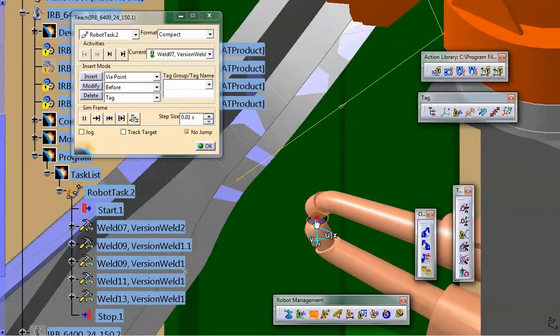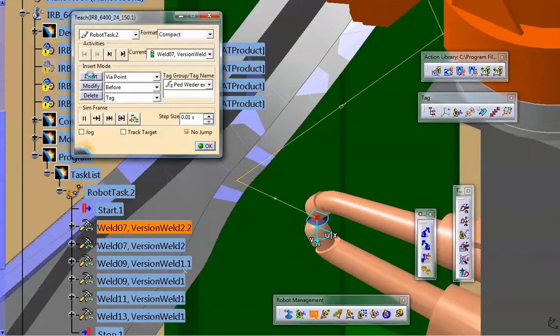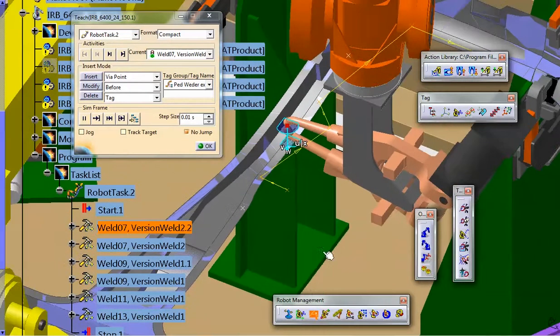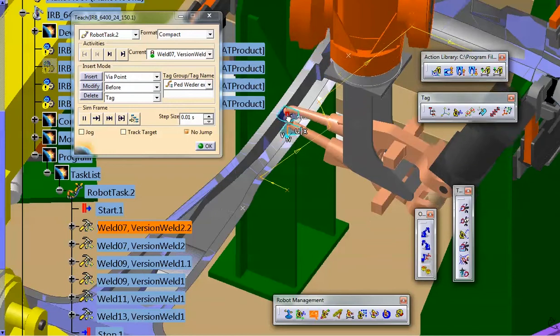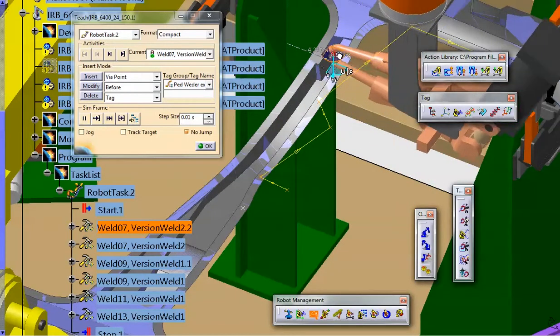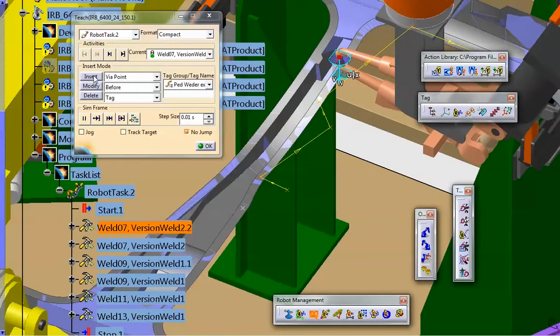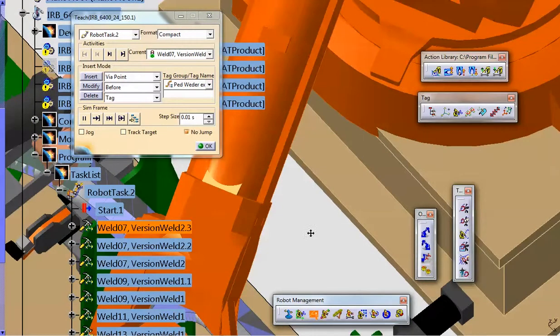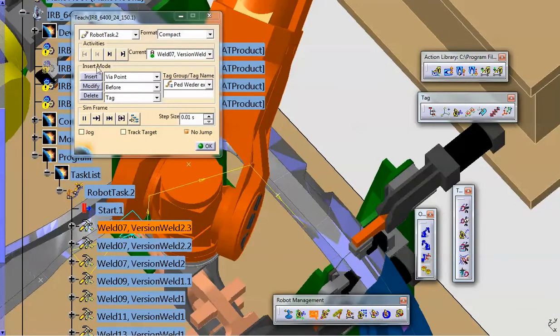And then we'll place another point away from the workpiece, lifted away, some kind of clearance point, or a pounce point as it's sometimes called, to jump into the work. And within the program this would be performed in a rapid movement, whereas the close-in work would tend to be done at a slower speed.